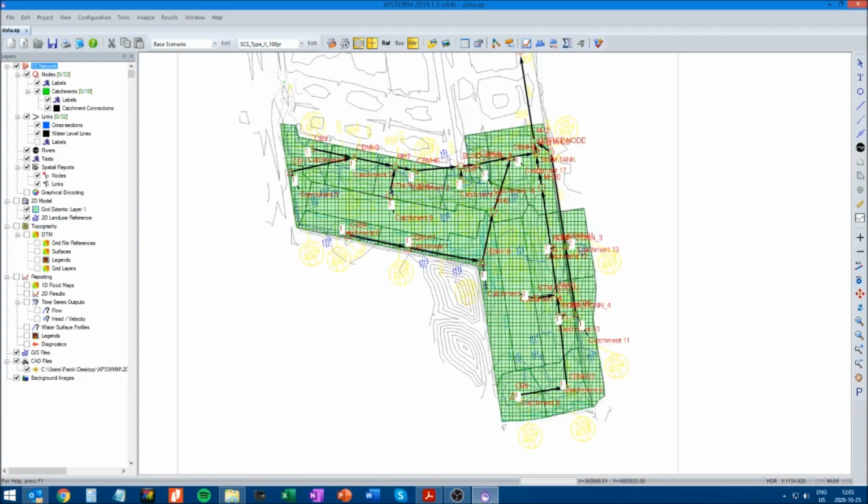That way, if there is extra capacity in the adjacent catchment, the catch basin will spill and will not overflow. Overflow means that the model does not account for that runoff anymore, and it's not a good condition to have in the model. It just signifies an error.